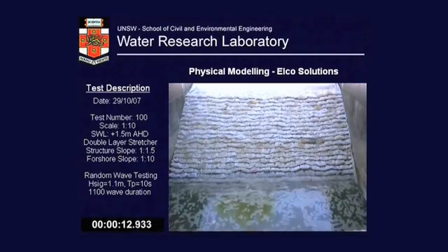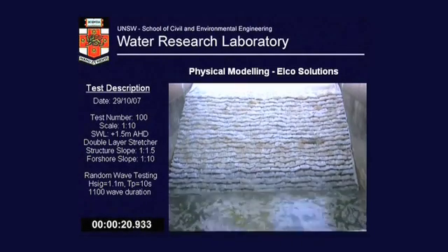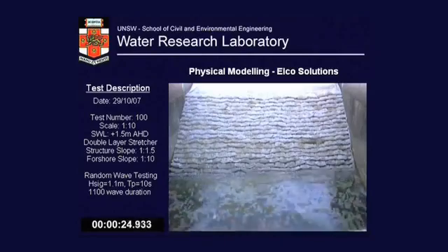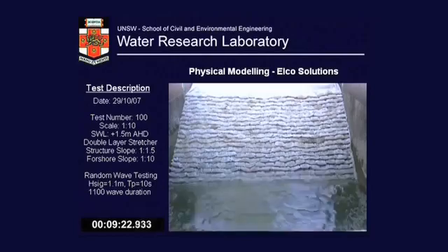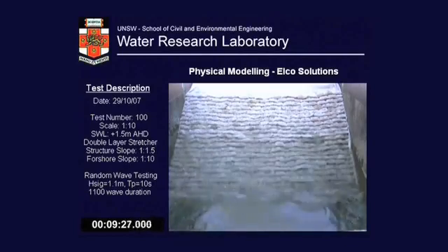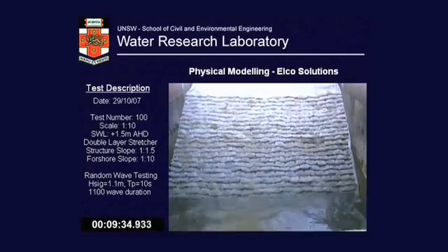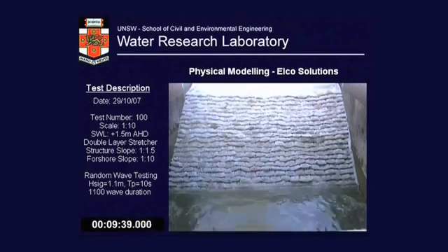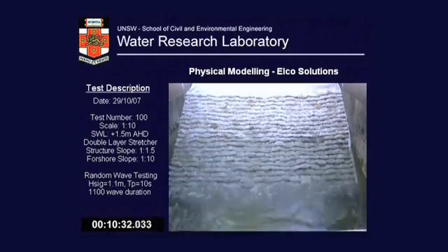It's sped up. It's a different time scale to what you actually see. Right, so these are waves. So this is about a 1 in 10 scale of model testing. And you'll see, if you look, damage is starting to initiate around here. You can see we have lost a container down the bottom there as well. So nearly all the damage occurs within the waterline, so obviously you don't get damage up here, but basically above and below the mean sea level.